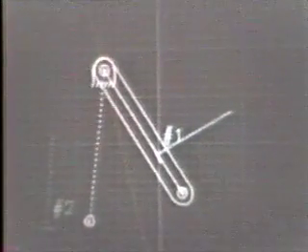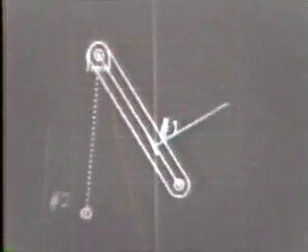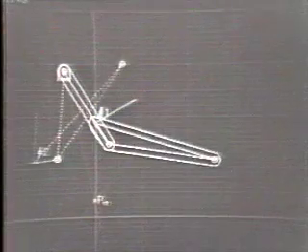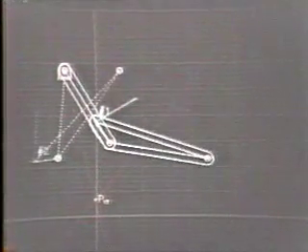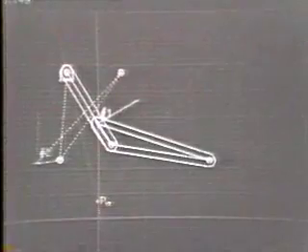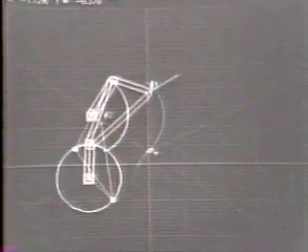As you see, the link is shown both in its reference or number 1 position, and it's also shown dotted in its alternate number 2 position. Grabbing a second moving pivot off the list of icons on the side of the screen completes the coupler triangle for the mechanism. You'll notice that default link shapes have been chosen for display in this case. Since the designer doesn't have actual pictures yet established for his various links, he chose to use the default shapes as shown. Notice that the coupler triangle changes shape and distorts to reflect the instantaneous shape of the mechanism.